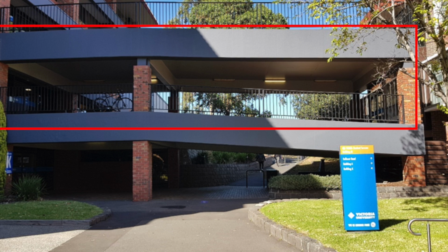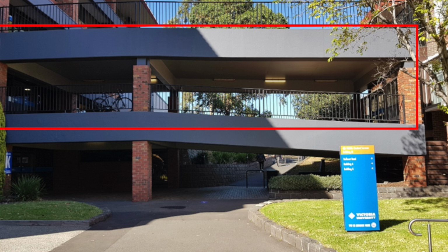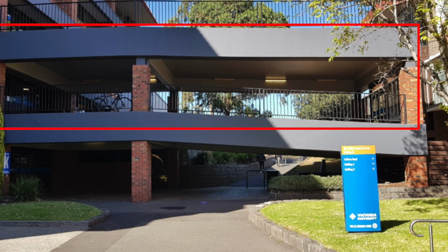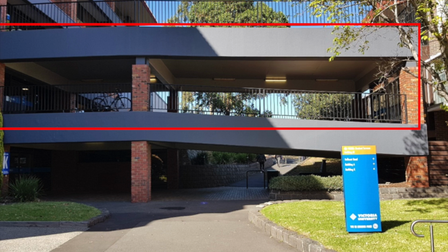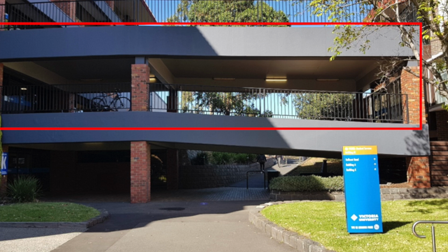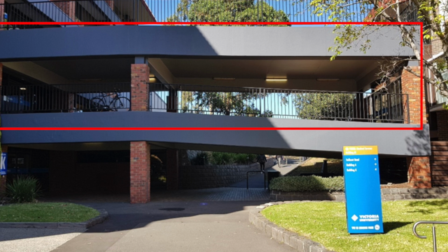The third section of the bridge we calculated is the concrete slab. The concrete slab also has a density of 2,400 kilograms per meter cubed. The volume of the concrete slab is 50.28 meters cubed, which resulted in a mass of 120,672 kilograms.